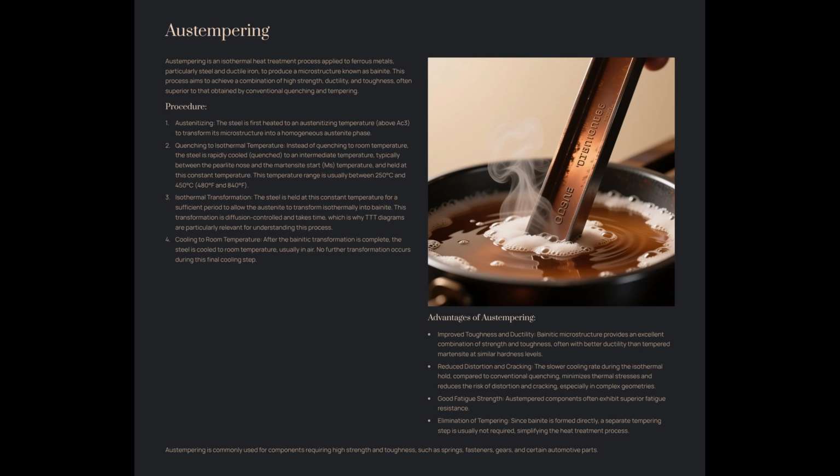Martempering. Martempering, also known as marquenching, is a specialized heat treatment process for steel, designed to minimize distortion and cracking that can occur during conventional quenching, especially in complex or large parts. It aims to achieve a fully martensitic microstructure with reduced internal stresses.